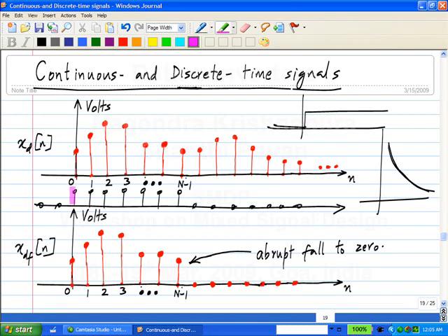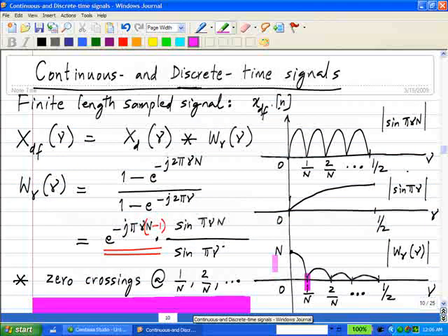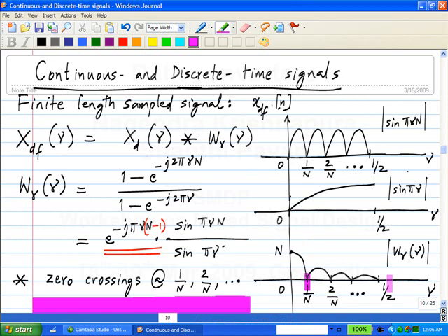If you look at it, it's the Fourier transform of the window which had all this junk. So this, when you convolve with the sinusoid, appeared around the sinusoid. So you have to fix the window.